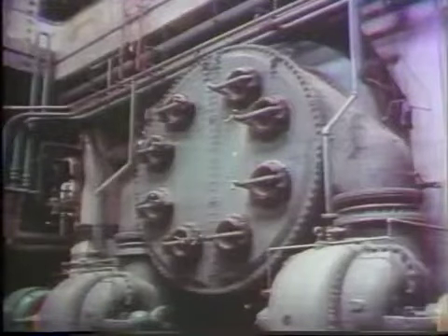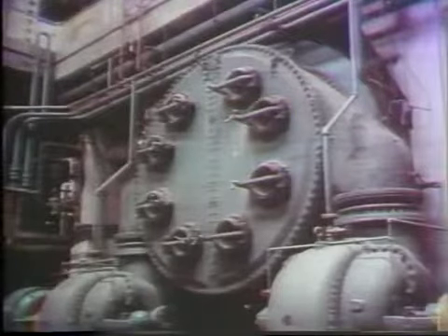Nitrogen oxides present a different problem. Scrubbers and other external anti-pollution equipment do very little to reduce the amount of nitrogen oxide released by a boiler. Instead, we control their formation by controlling furnace temperature. A number of methods are employed to reduce the temperature of furnaces. Adjusting the fuel-air ratio will slow down combustion, and recirculating flue gas back through the furnace will accomplish the same thing. You'll need to find out what methods are used in your plant to reduce the amount of nitrogen oxides released into the atmosphere.